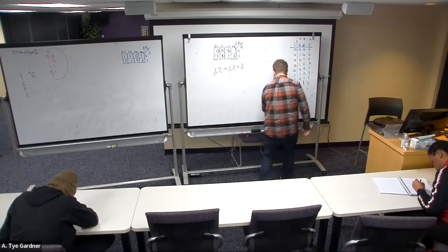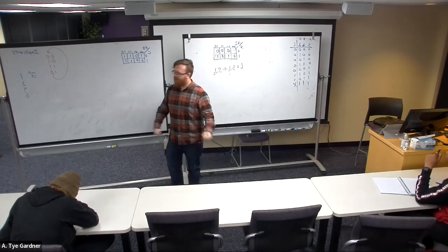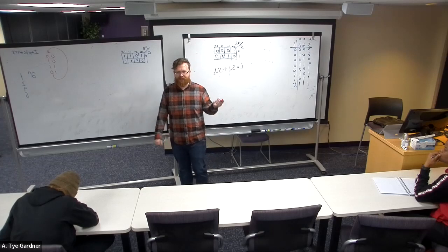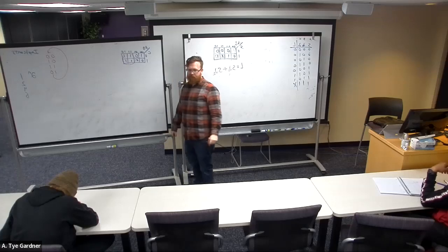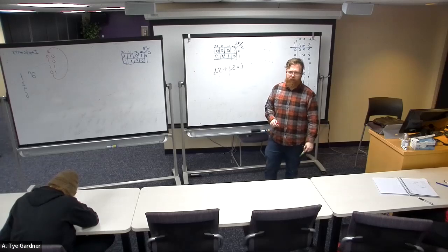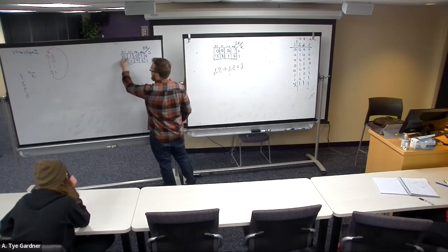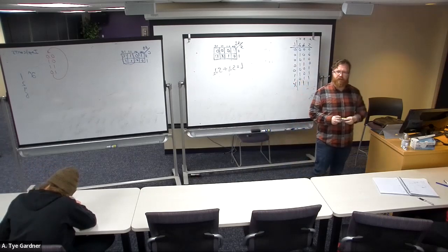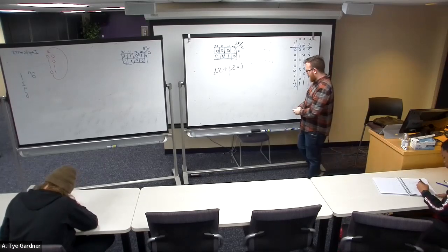Okay. I grab my implicant. Remember how I said rectangles or squares? Because squares are rectangles anyway, so I could just say if it's a rectangle, you're fine. There. I have one more one. I could circle it on its own, but I'd be wrong because it is logically adjacent. Remember that wraparound question? That was a good question. There we go. I've completed coverage. Take a moment. Write me the minimized equation. If you have any of the implicants, you write the equation.